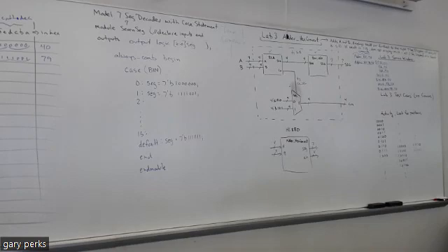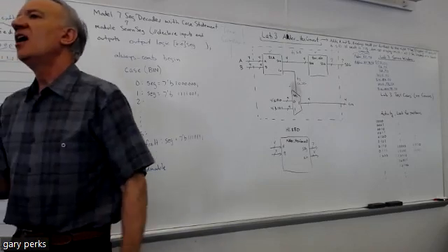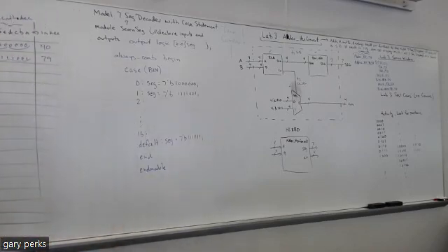So are you using the carry out bit to just shut it off entirely, but then have the clock flop back and forth, lighting up the 2 different anodes? But before that, did you say clock, like the word clock? Yes. Okay, so you know what a clock is, because we haven't talked about that, but a clock signal is like this. That's another distinction between combinational circuitry and sequential circuitry. Combinational circuitry, what we're dealing with right here, has no clock signal. You're going to see when we get to sequential circuits, which have memory, you need a clock. So yeah, there's no clock here.